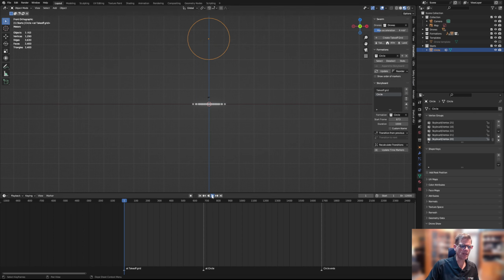But you can see when we hit play here, the drones should actually start flying up to the circle. They are. We can monitor on the statistics here the maximum velocity. So they're coming up at 2.9, 3 meters per second. And we can see the minimum distance between the drones is 2.1 meters right now, 2.2, and 3. So you'll find, thanks to the Skybrush folks that have pointed this out, that the minimum distance during the transitions can actually get down to your normal spacing for your formations divided by square root of 2. So that 2.1, that's pretty average to see on a transition.